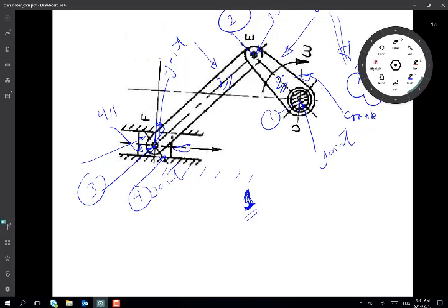into the linkage at the crank's end, you imagine that there will be some resistance to the motion at the slider's end. So that will be the output link, which will take the input torque and transform this into forces which you can use at the slider's end. We can possibly be cutting some metal, it can be part of a machine tool, or maybe just pressing some components or whatever sort of thing.